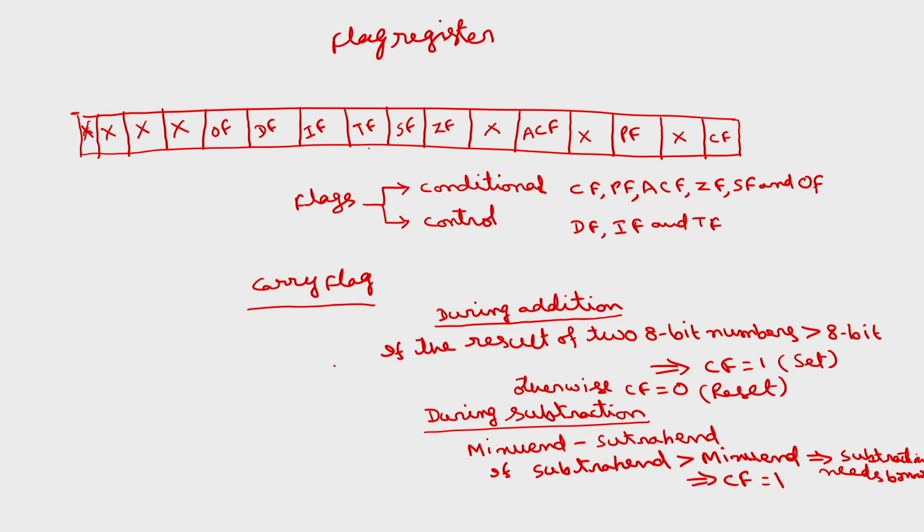So, in that case carry flag is set. If subtrahend is less than or equal to minuend, then carry flag will be reset.